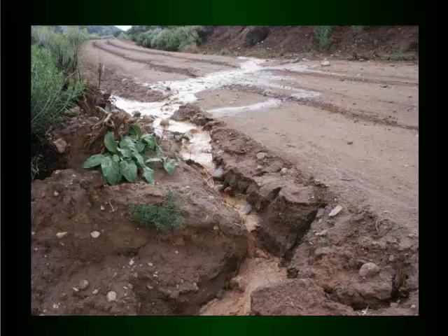This is an example. This happens to be Red Creek Road again. The ditch is obviously not functioning because water's coming out of it. You need a culvert here to kick the water across. There happens to be a berm on this side. This drops down into a notch that you could stack a couple domestic cows in. It just drops like that. Runs right into Red Creek with no filtering.